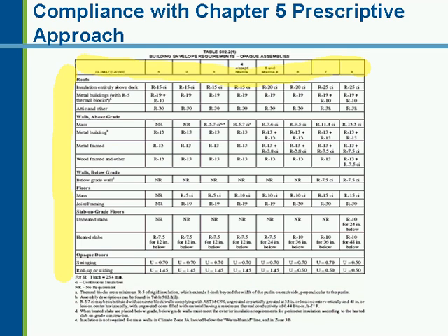And based on building assembly type and climate zone, that will dictate the insulation R value requirement, or as far as opaque door goes, the U-factor requirement for each of the different assemblies. And there are multiple types of assemblies represented within each category. For example, roofs. Your first category for roofs will be insulation entirely above the roof deck. So it doesn't matter what type of assembly you have underneath that. If your insulation is installed on top of the roof deck, then you would follow that category.